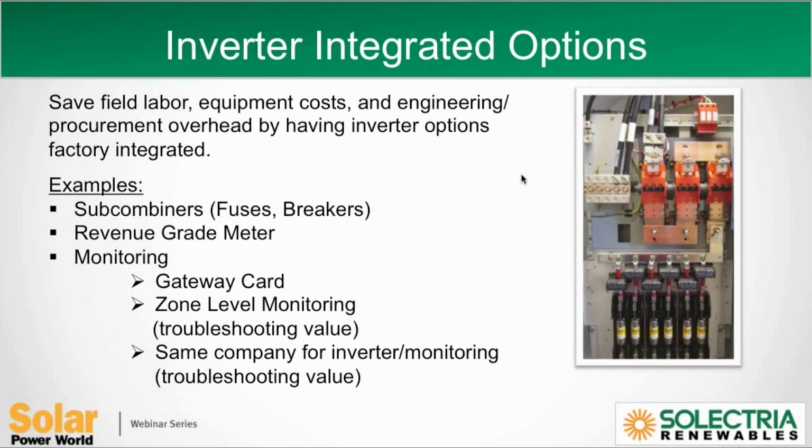Ours is called SolarInView. So we log into the SolarInView website and are able to talk about things that maybe the customer is seeing, and help the customer with troubleshooting issues that may be happening in the array. For example, why does the daily production curve have a chunk taken out in the morning? Well, maybe there's shading in the morning. From an application standpoint, it's helpful to be able to quickly log into web-based monitoring and provide that good support.